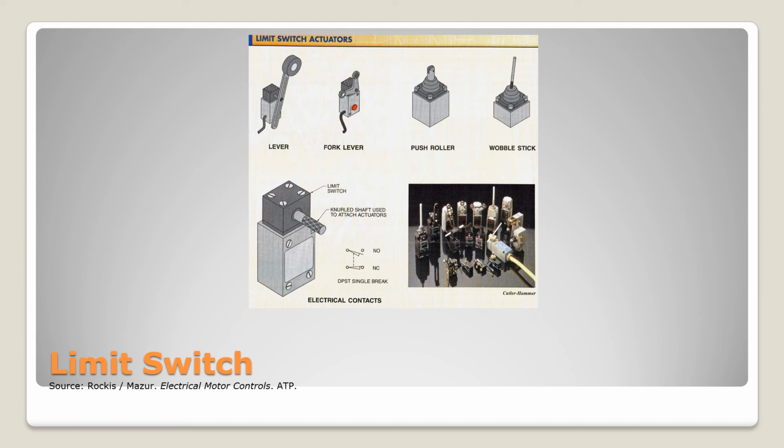A normally open set of contacts is a contact that when you hold the switch in your hand, there is no continuity. In other words, there's no connection from the input of the switch to the output of the switch. The switch has to be operated to go into a condition as this, for instance, you push the button and the contacts close. That's a normally open switch that is closed when you push the button. And since you have to actively push the button, so it's not in its shelf state anymore, we would say those are normally open contacts.